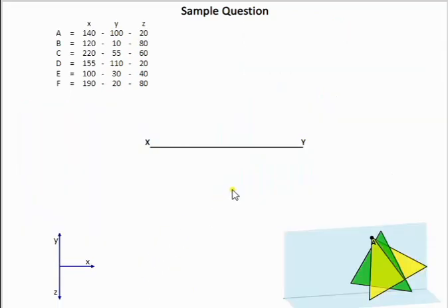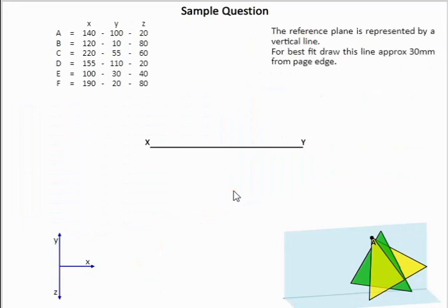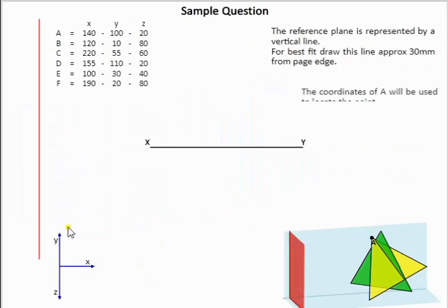Now looking at it here, this is setting up the sheet. We start off with a datum line at the side here. This datum line or reference line can be used for where we're doing all our measuring from. When we're measuring for all the X coordinates, we have to measure from the same point. This could be the side of your page as well.